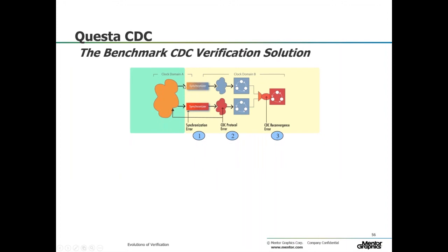For every signal that crosses from one domain to another, you have to put in a synchronizer. That synchronizer could be really simple. To go from a single bit from one domain to another, if you just put 2 flip-flops instead of 1, that's a single bit synchronizer. The output from that first flip-flop may go metastable, but the second flip-flop will make sure that metastability does not propagate forward into the rest of your logic.